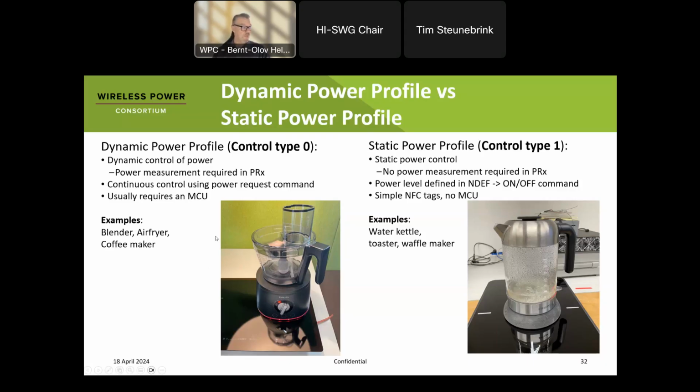But important for all these kinds of things is that we deliver the level of required power to the transmitter, because we do not want to get more power than we need, because that is just waste of power and that is generating a lot of heat. So the feedback loop is essential, and it is continuously delivering to the transmitter the level of power required.